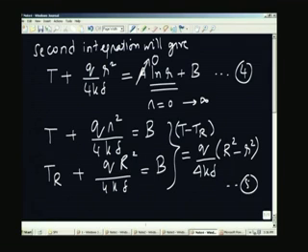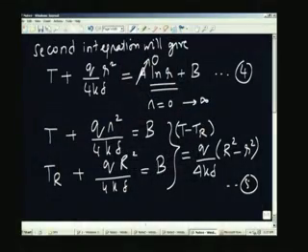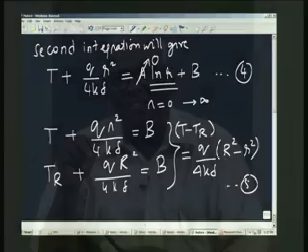We expect the temperature to be high in the middle of the foil, and as we go towards the periphery the temperature is going to come down to the value specified by the cooling arrangement we have provided. So, there is a temperature difference generated by the application of the heat on the foil, and this temperature difference is in a direction perpendicular to the direction in which the heat flux is applied. That is the basic idea in this particular gauge.